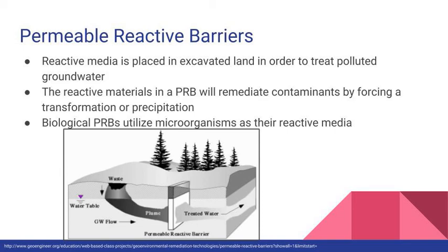These reactions can either be precipitation reactions, causing the contaminants to drop out, or redox reactions, causing the contaminants to transform into a less toxic compound. Ideally, the barriers are reactive enough to trap pollutants and permeable enough to allow the flow of water, but not pollutants. PRBs are meant to be passive, with little energy input, inexpensive, readily available, and accessible.